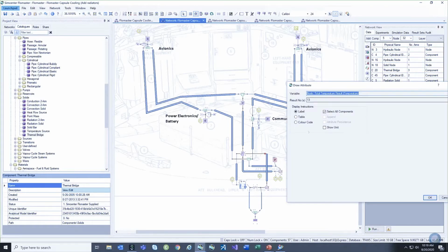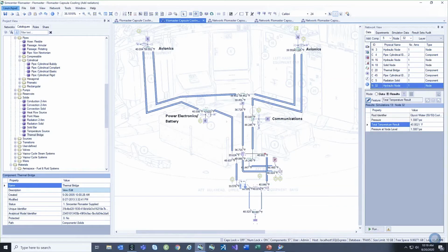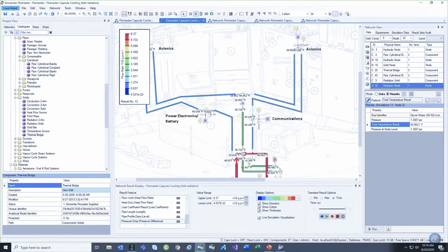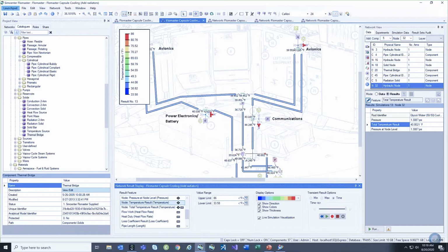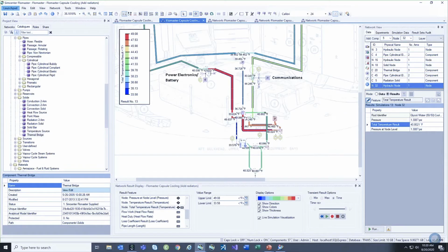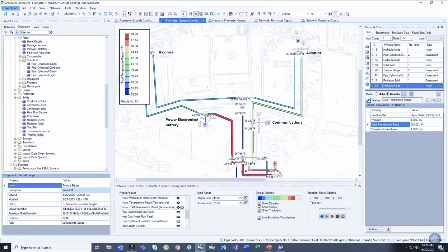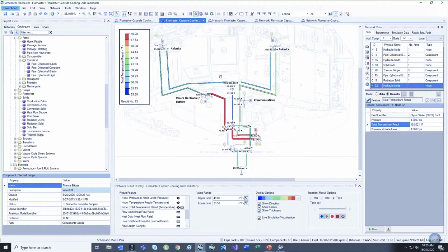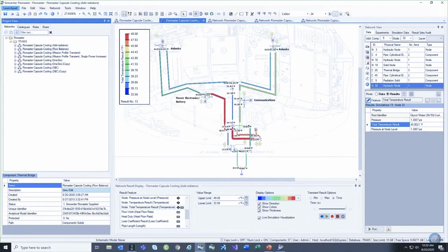And no flow balancing anymore. I've actually left the restrictors out, but you can see we run and it takes a few iterations, but it succeeds. And we can click around the model and look at, let's say, temperatures in our model everywhere on the screen. Temperatures are nice, but color codes are nicer. So if I want, I can actually just pop up a temperature profile, draw that right on the screen. So you can see that here. This is heating up, hot flow is going in here, gets cooled by the secondary loop and radiates out. So that is our steady state thermal model that we can use for sizing and model creation.